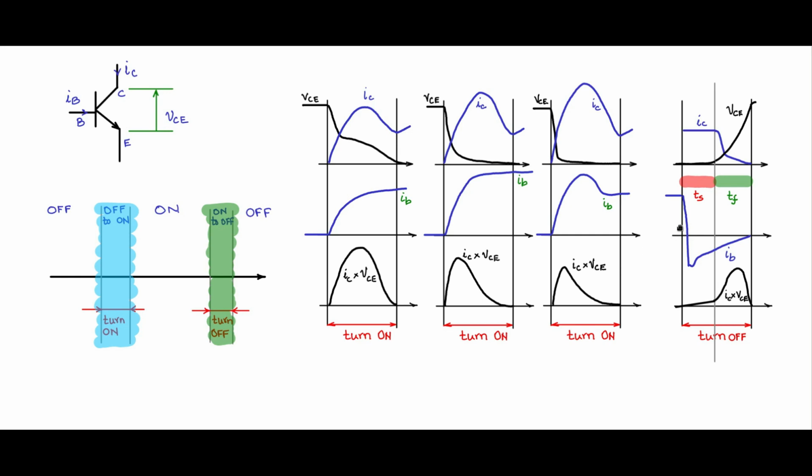So the nature of the base drive that we have to give, look at this. This is the turn-off portion. You give a surge base drive for on, and then you will have an on state base current, and while turning off, we have to have a facility for negative base current so that current can flow in the negative direction and sink somewhere.